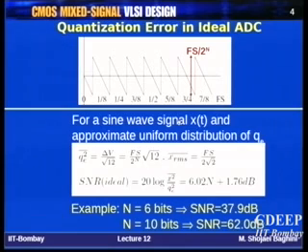Now, from this, the first specification of an ADC is the maximum SNR one can achieve with this ADC. Even with ideal conversion you get this quantization error. If you look at it as a kind of noise, there will be a signal to noise ratio specification which tells you what is the best we can achieve in this ADC, where everything is ideal.